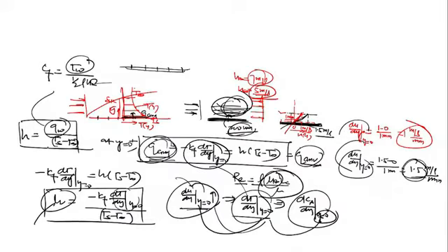Its analogy is there. It's the friction coefficient, that is the heat transfer coefficient, and tau_w is nothing but mu into du upon dy at y equal to 0. Since the velocity gradient at the wall is going to change from one location to another, yes or no, the velocity gradient is maximum at the leading edge and keeps decreasing. That's why the friction coefficient decreases, and is infinite at the leading edge. Yes or no? Same thing here: dT upon dy at y equal to 0 is maximum at the leading edge, and that decreases along the length of the plate. Clear, beta?